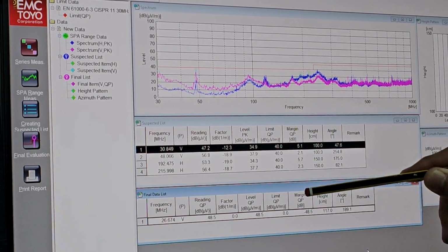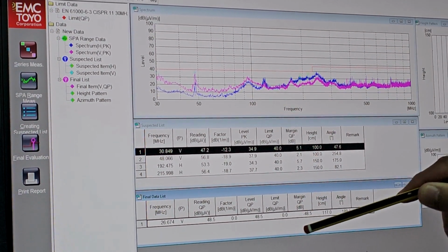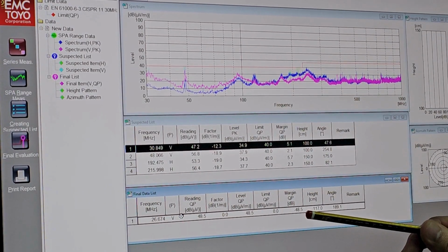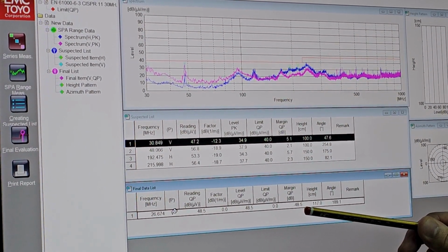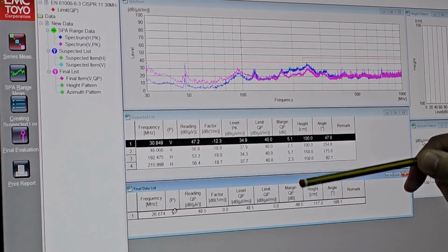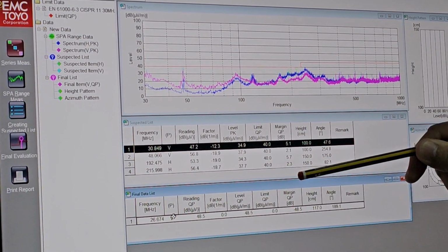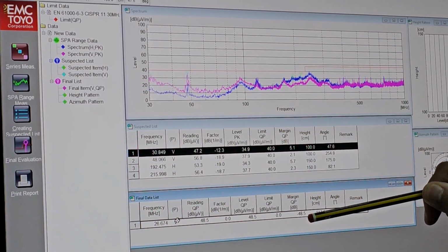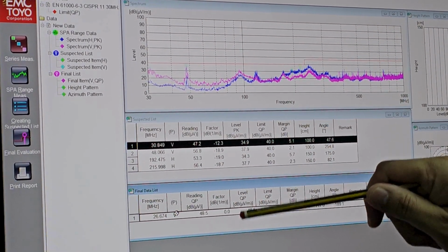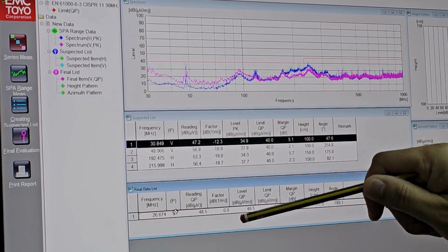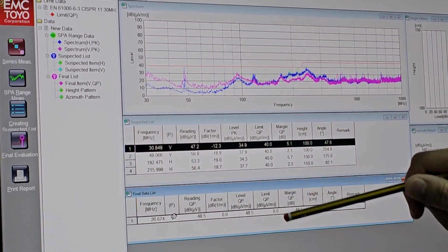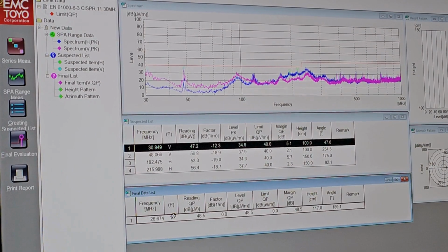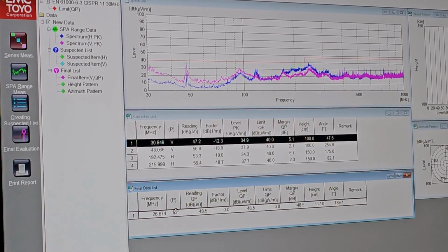Okay, so over here this draws a conclusion. What will be the margin? Over here you can see that this actually failed the test. They fail at minus 48.5, which means that this DUT does not pass the EMC test and measurement. They fail at this level. And the rest of the values you can see are all here. These are all the values that they capture, which is 48.5, and they generate this so-called margin. So in short, they fail this EMC test and measurement.